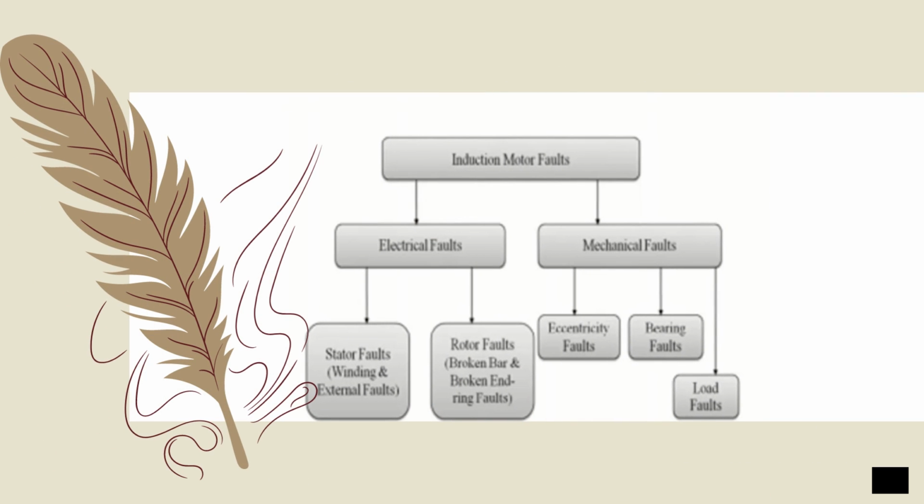In an induction motor, there are two kinds of faults: electrical faults and mechanical faults. As you can see in the slide, there are stator faults and rotor faults. Stator faults are winding and external faults, and rotor faults are broken bar and broken end ring faults. Mechanical faults include eccentricity faults, bearing faults, and load faults.